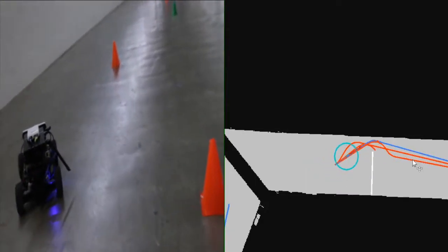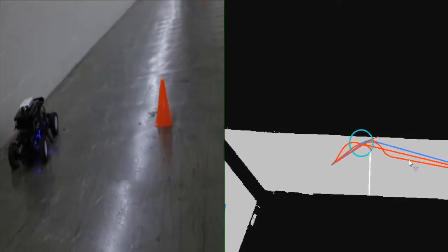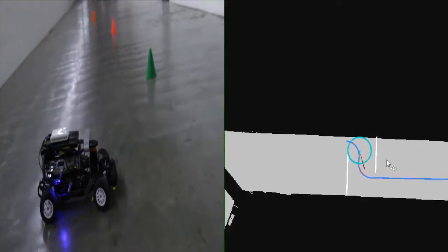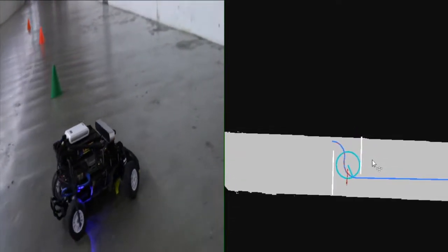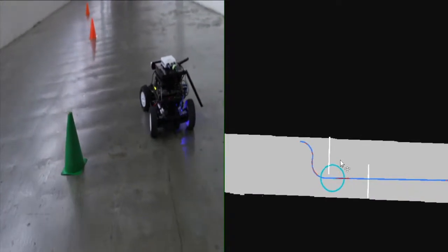During the RSS challenge, the robot successfully navigated the tunnels and correctly drove around all cones. The course was completed at a slow pace because real-time path planning required additional computation time. Initially, the robot would plan multiple loops around each cone. This was resolved by ignoring cones seen close together.